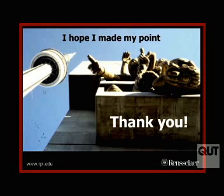And one of them in Houston lasted for 6 months, and 2 of the vertical axis turbines flew off and landed in a park and caused damage to 2 cars. Again, because of fatigue, like you were talking about. And that's on the internet. You can look at YouTube, you look at Discovery Tower, Houston, turbine failure. Someone was in the park with a video camera, that's all on film. And you can't insure them. So I think they're mobiles. They're not really for effective generation of energy.